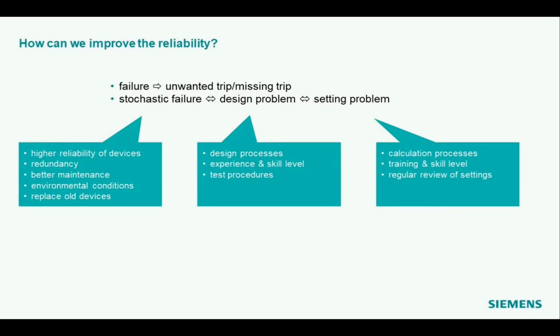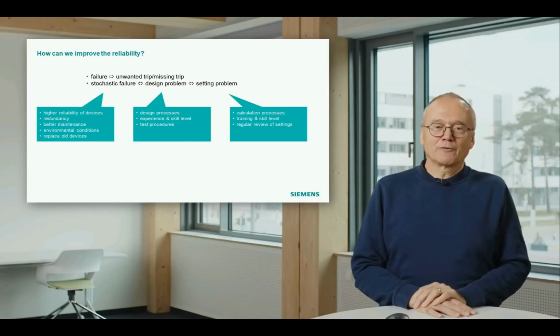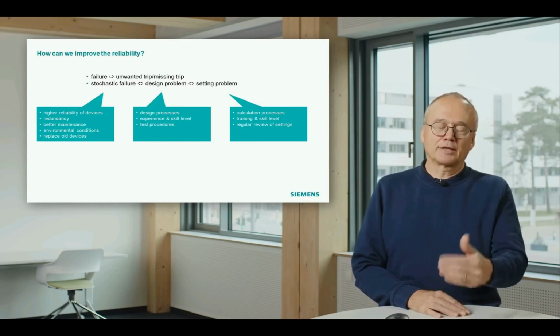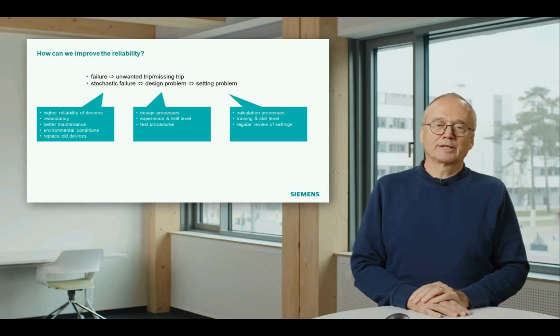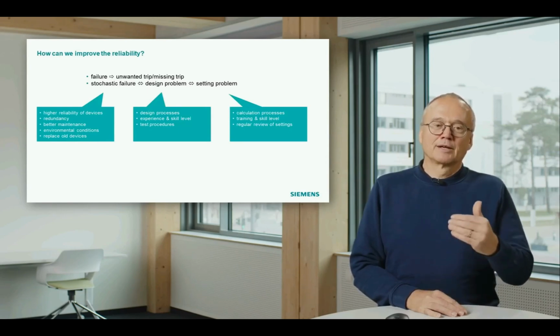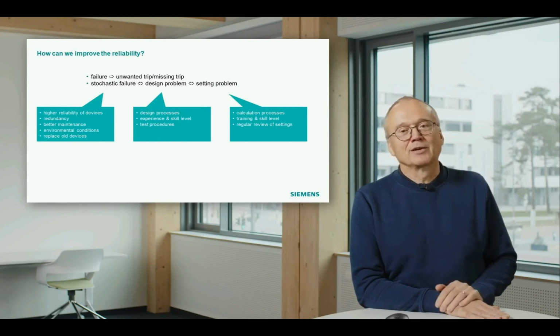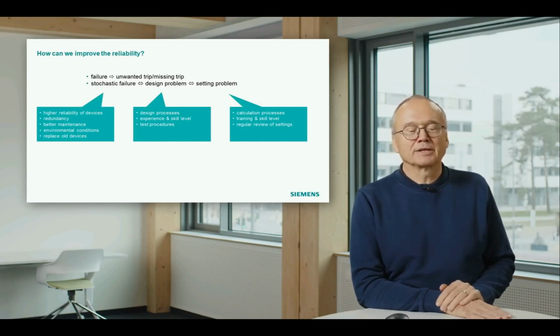So you see, there are different components you have to have a look at if you want to improve the reliability of the system. It is not only the MTBF of the protection relay, and that is the message I want to give with this chapter. And think about this example with front door and back door. I think that's a good equivalent in this case to motivate investment at the right point. So that is the end of the reliability chapter, and after that we will do part 2 of building a protection scheme.